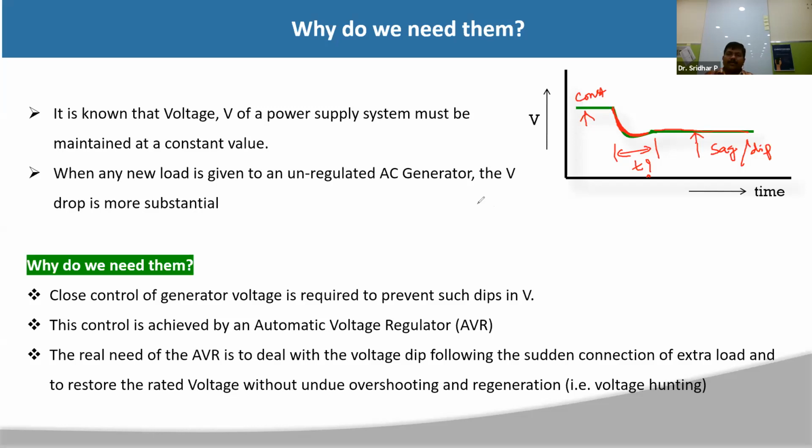Generally, not only voltages but electrical parameters in power systems are represented with per unit values. So if it is constant, you should always see that the voltage is at 1 per unit. If the voltage is 1 per unit, the system is okay. We say voltage dips many times, or these are under voltages, or more technically you can call them voltage sags. The next one is over voltages, and the next one is swells.